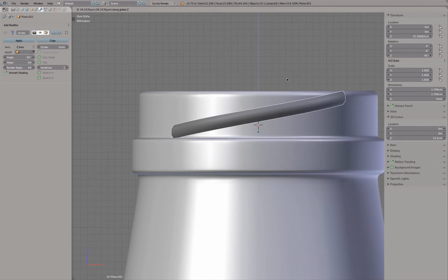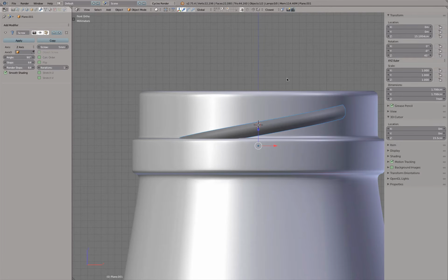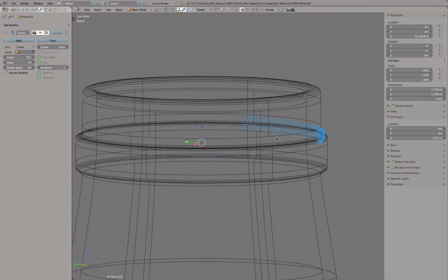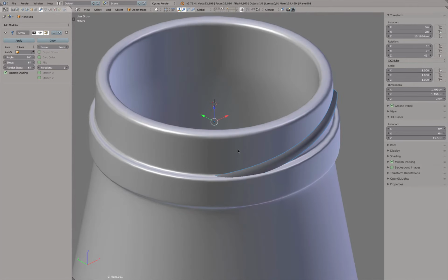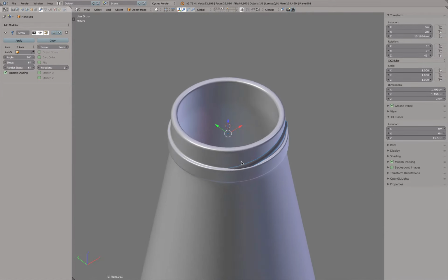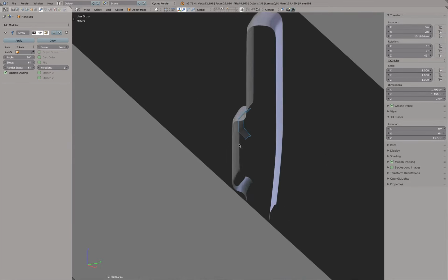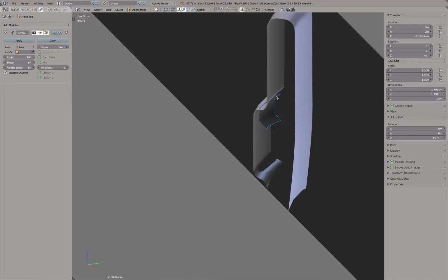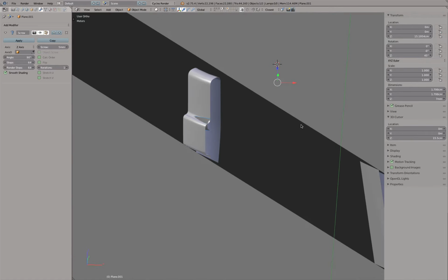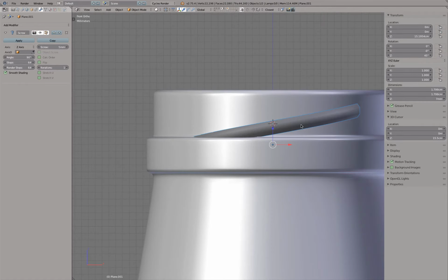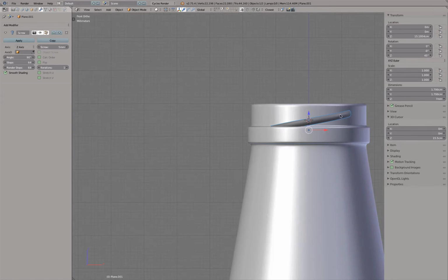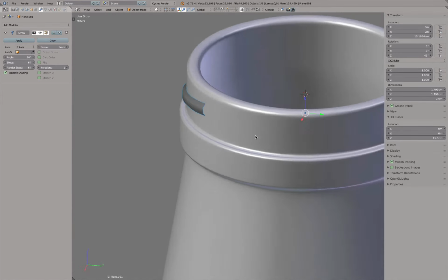There, GZ minus .002. Okay, pretty much should do it. Let's be really precise to make sure that it really intersects correctly. So from this view with Alt B, let's make a cut section view so we can see, yep, the ends actually go through the part and rest inside the model. So that is perfect, because that's what we need. It doesn't have to rest on the model, it has to cut through it and stop inside.